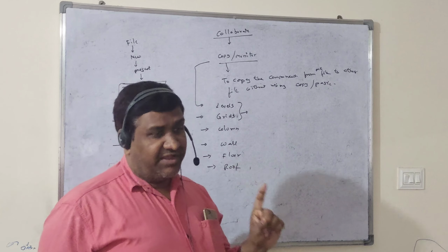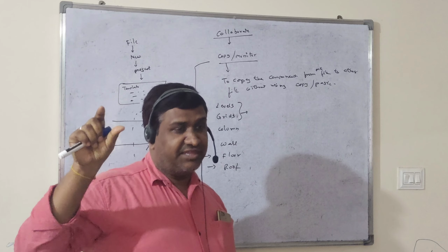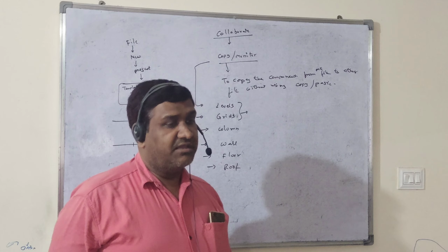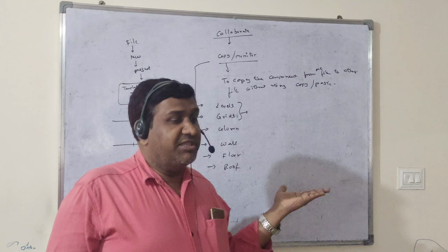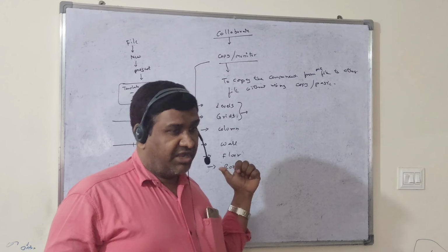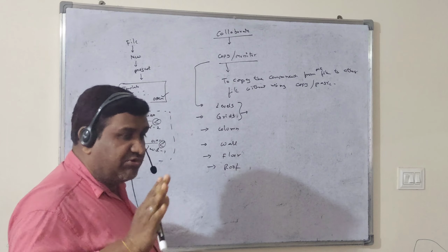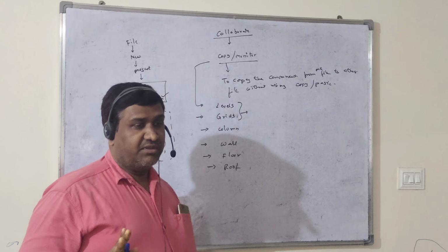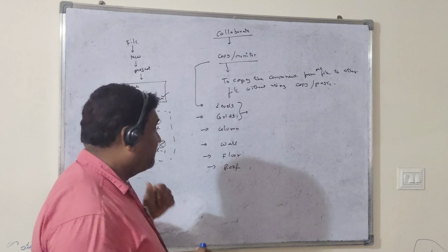When you delete these levels, automatically in your project browser the floor plans and ceiling plans will be deleted, because there is no level, so there is no floor plan. Nothing will be there. It is deleted automatically when you delete these levels. If the floor plan and ceiling plan are deleted, don't bother about this, because we can take them again, no issue. These are views of the project, and in the project browser they appear as views.